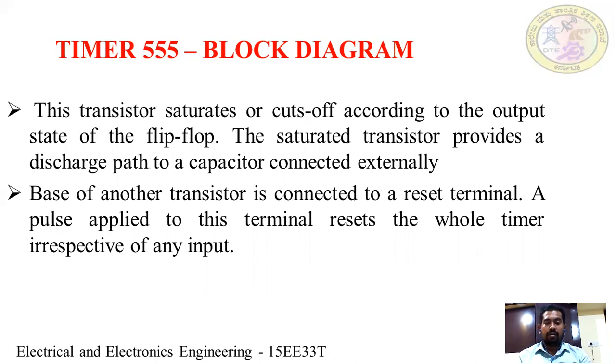The transistor provides a discharge path through the capacitor, which is connected externally. The base of the other transistor is connected to the reset terminal. A pulse applied to this terminal resets the whole timer irrespective of any input.